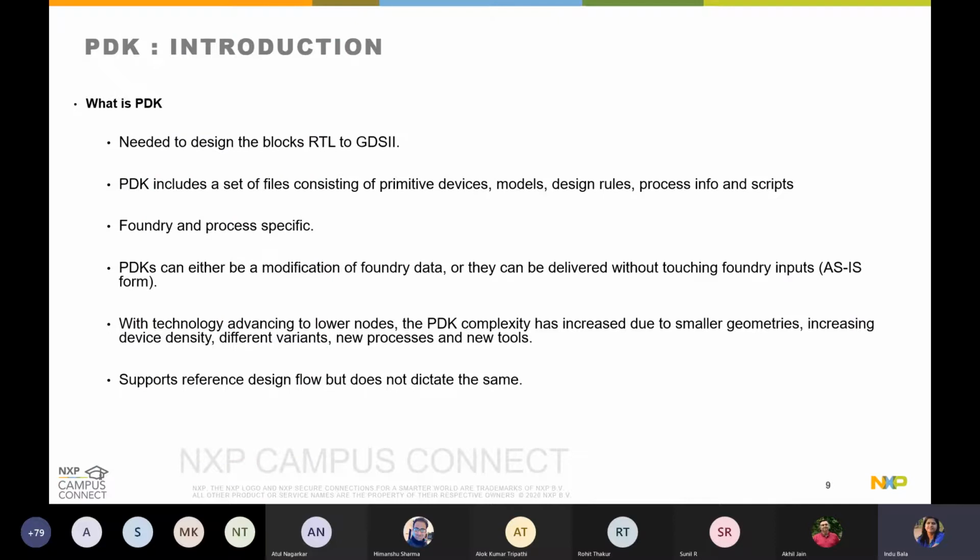You use certain tools inside that flow, or go a certain way, you use a certain netlisting process, or a different combination; every design team has its own flow. So the PDK's intention is to support those reference design flows for the product that is being created, but the PDK should not dictate the reference design flow. If the design team needs some variation or update, or wants to do things in a different way, then the PDK always needs to adhere to that and support those flows.